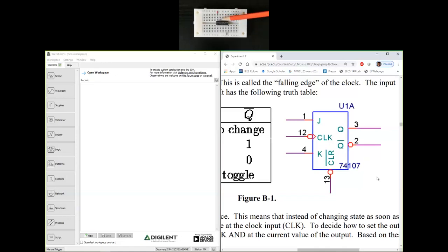So if you look at the proto board here, you can see pin number 14. So I have a notch here, and there is a bubble at this edge, the bottom left, which indicates pin 1. So if I go counterclockwise, I have 1 through 7 and 8 through 14. So I've connected pin number 14 to, let me switch this on.